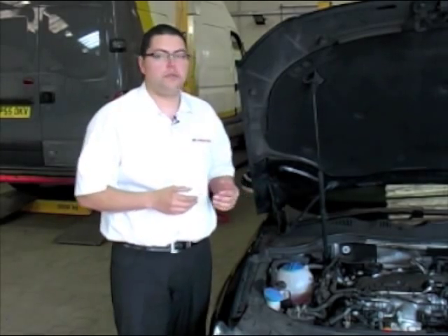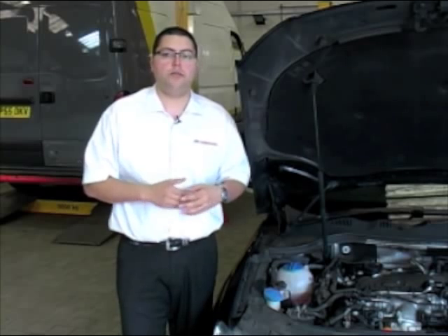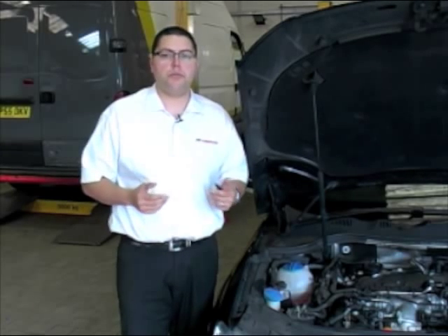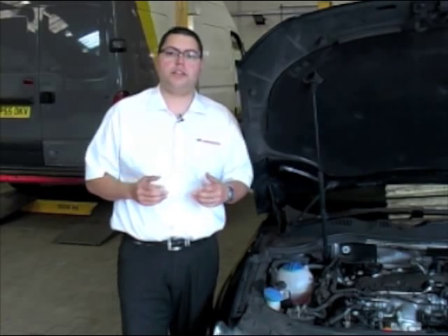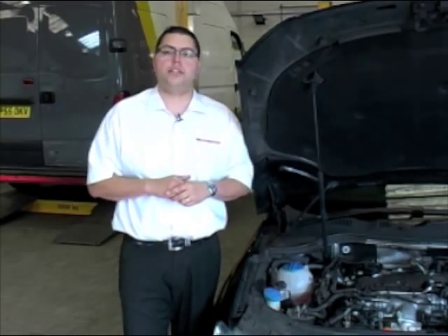After going through these checks, we've now found the air mass sensor is faulty and we'll be looking to replace it. It's always important to do these diagnostic checks because air mass sensor faults is the number one question on our technical helpline.